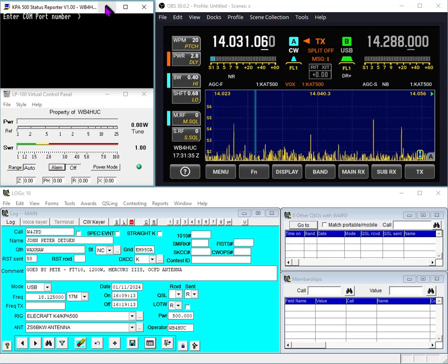There we go. So when you start the thing, you specify two parameters. One is the COM port number that the amp is connected to, and for me that's COM port 5. And then you specify the serial port communication rate, which for me is 38400.